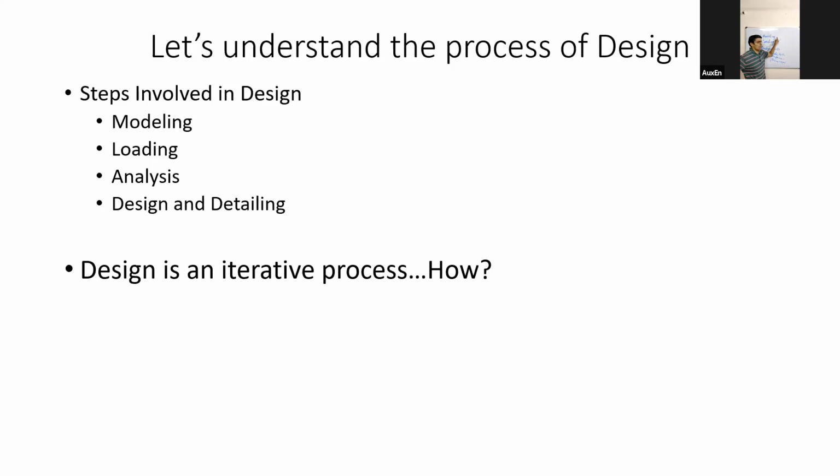Because unless I select a size, there would not be any stiffnesses that my analysis can take into account. And if there are no stiffnesses, there is no stiffness matrix that can be formed. So there is no analysis. If there are no stiffnesses defined, there is no analysis. If there is no analysis, there is no design. So we have to have some basic sizes if we are to perform analysis.